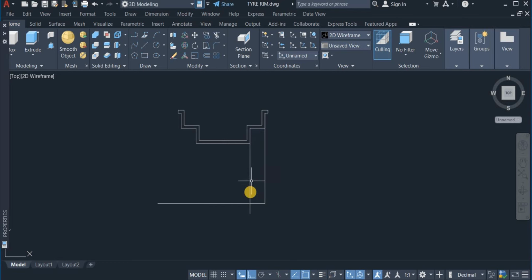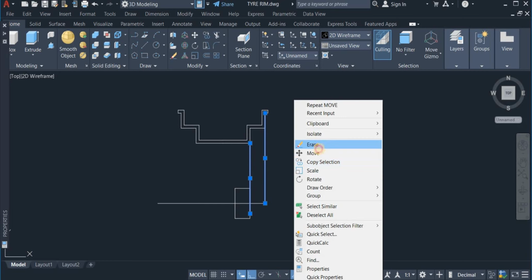Okay, now I'm going to draw a rectangle. Draw a rectangle of 50 by 100. Enter 50. Then click the tab key and enter 100. Okay. Now I'm going to move this rectangle from this point and drop it right here. Okay, so I don't need these two lines now. I'm going to wipe them off. Right click and delete these lines.